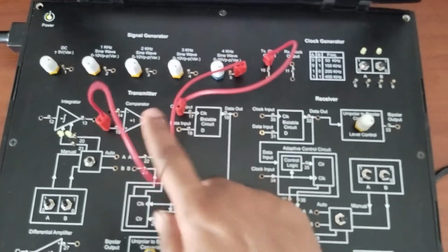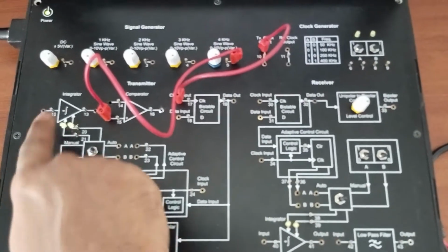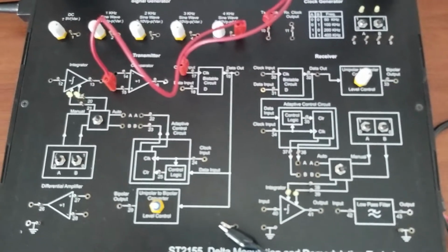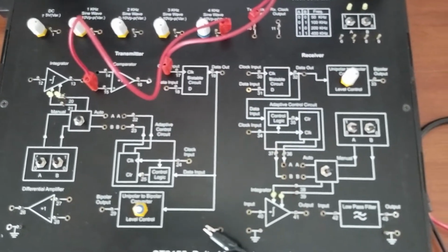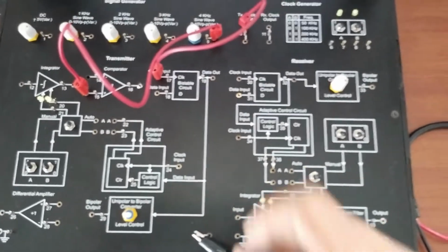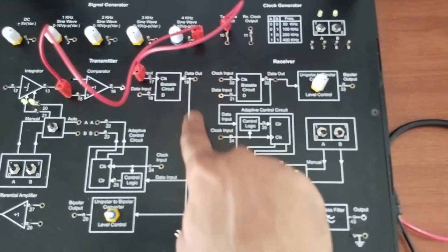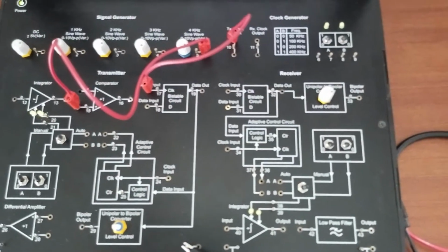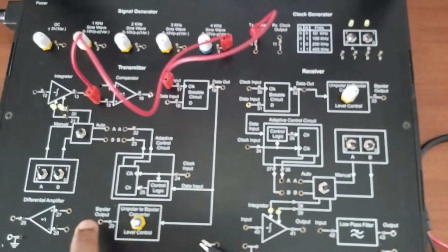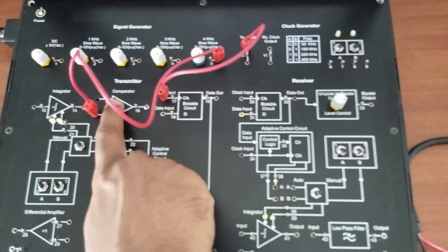Why I am connecting this: in digital modulation, the output of the circuit is given to the input again to compare this data to get back only zeros and ones of the digital data. That means each and every sample is allocated only a single bit. For that purpose we get the digital data output as unipolar. To get the same signal as one more input to the comparator, the unipolar data should be converted into bipolar, and the bipolar data is given to the integrator. That integrator output is given to the inverting terminal of the comparator.